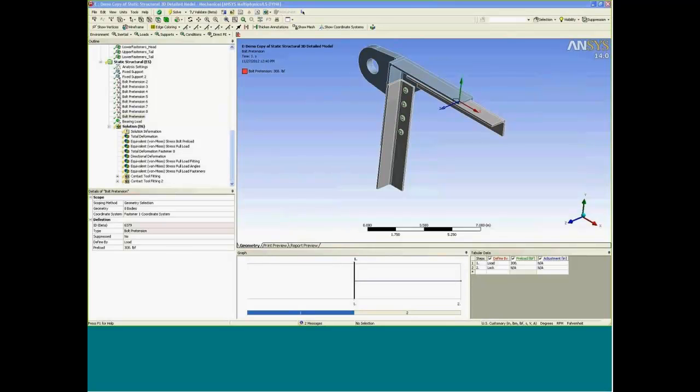In terms of results post-processing, in these assemblies, are you interested in just looking at the load in each fastener, maybe even in a 3D scenario, and using a handbook calc to determine the underlying stresses? Or are you interested in, hey, I know I just need a net section stress in the parent material because I know the KT and I'm going to do a fatigue analysis? Or is it most important to you that you get the detail stresses in all the parts? Is it the detail stresses in the parent material or the fastener itself? So what type of information is most important to you?